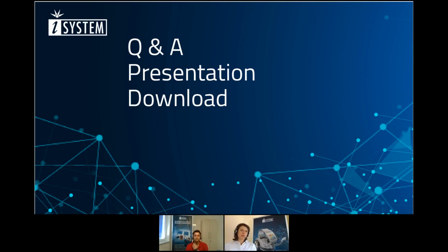Another one, I would like to come to the SWO. What is the maximum clock speed of this SWO output? Directly jumping to the answer, the SWO interface is an asynchronous interface. You do not have a clock line, but you do have a data output line.